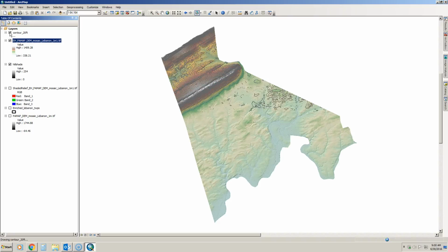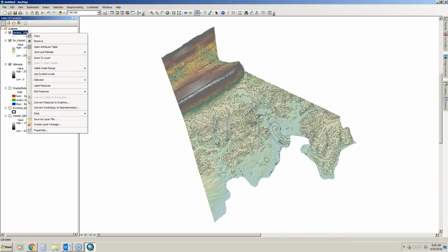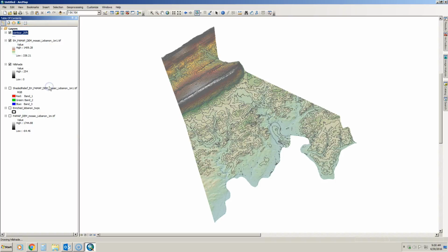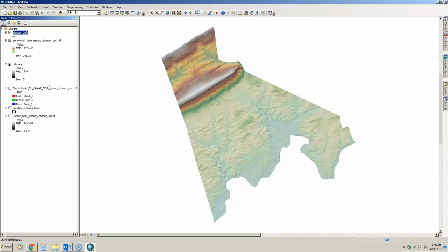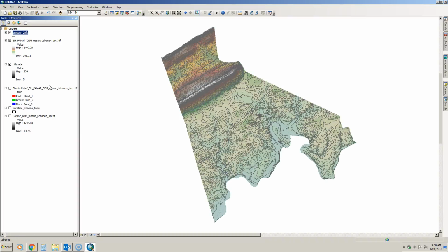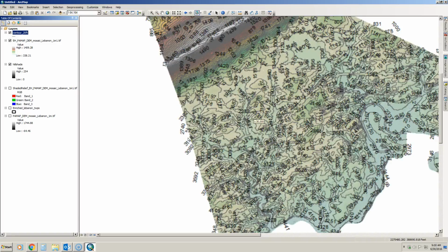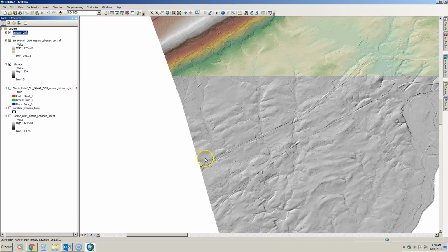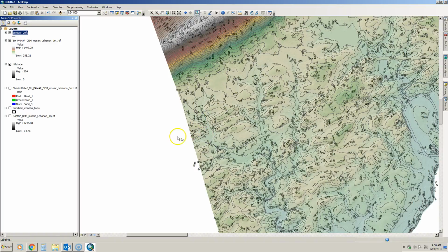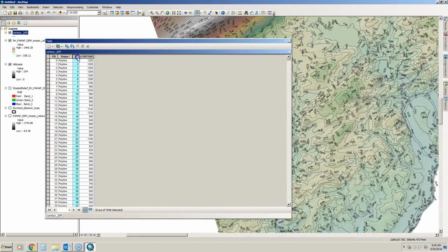And we probably want to label our contours. And something to make note of that messes people up a lot of times, when you go to label them, it's going to label by the incorrect field, which is problematic. If we look at these, we had a contour interval of 20, and when you look at these, none of these are a multiple of 20. And the reason why is because it's labeling the ID field rather than the contour field.